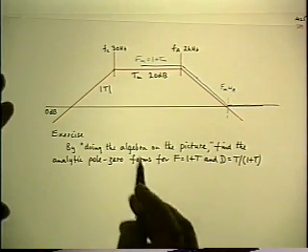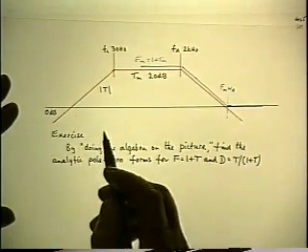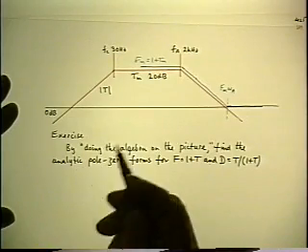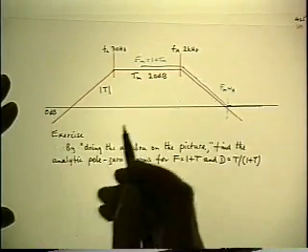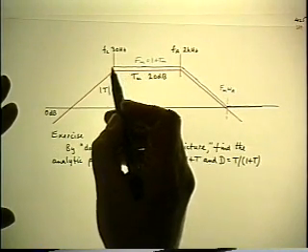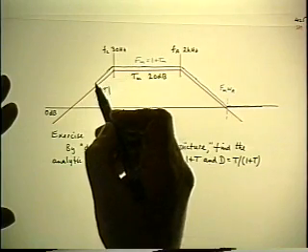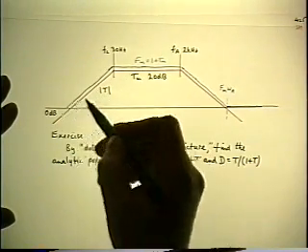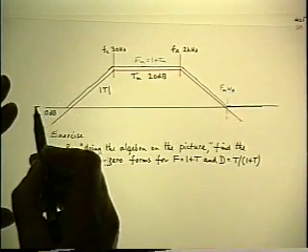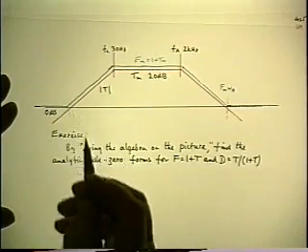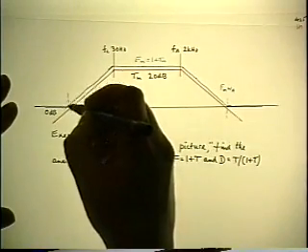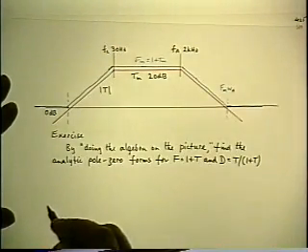The only difference this time is that we have something else going on in the lower part of the picture, but it's simply a reversed frequency direction, and the construction obviously will be exactly the same. So going down in frequency, the 1 plus T will have the same corner as the T, and that will continue parallel with the T until when the T drops below 0 dB, 1 plus T again will level off at unity or 0 dB, extrapolate the asymptotes as before,